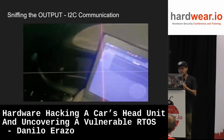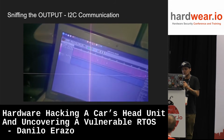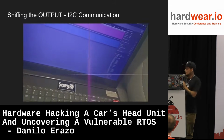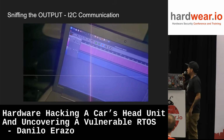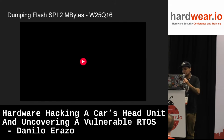This communication is captured through a logic analyzer. So in the boot process, as you can see, there is communication. So the system will actually read this data. Okay, perfect. After that, let's dump the other flash, which is the WB25Q16.